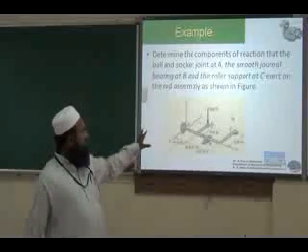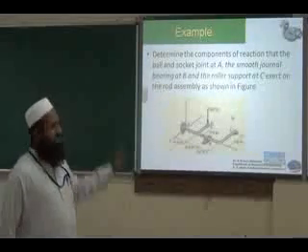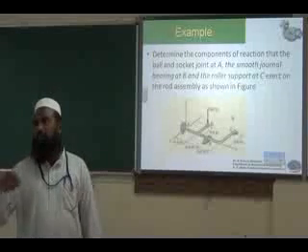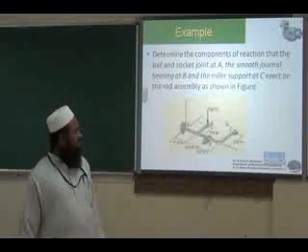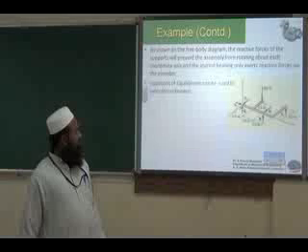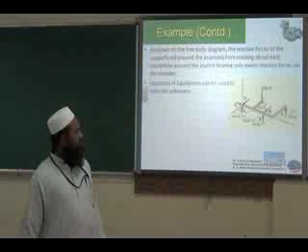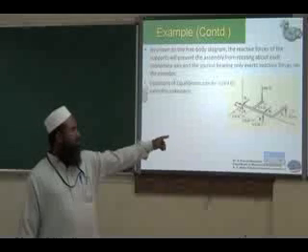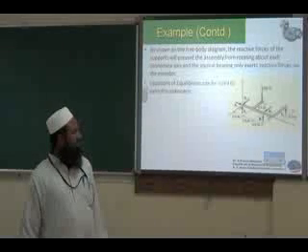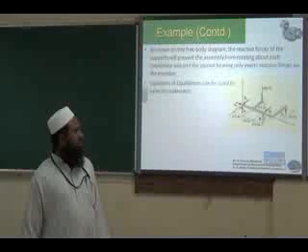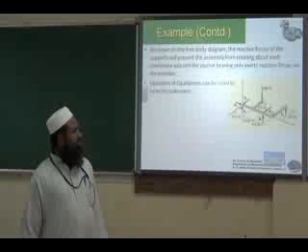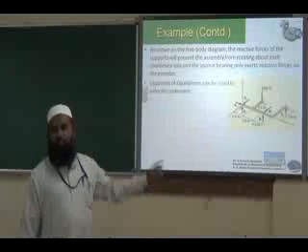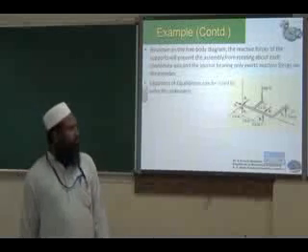So in order to find out the unknowns, first we have to draw the free body diagram of the bent tube. So the free body diagram will be like this. You will have three reactive forces at the ball and socket joint. At the bearing, it has two reactions: no movement in x direction, no movement in z direction, so two reactions. And at point C, one reactive force.